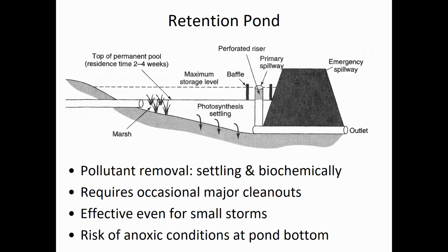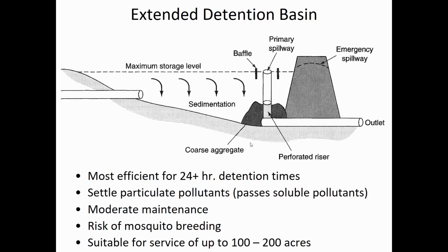But the issue here is that this extended detention basin is dry most of the time. And so it's much easier to maintain. You don't have to drain it to maintain it. You just have to occasionally, if there is a lot of sediment at the bottom, send a crew in there with a backhoe or some sort of shovel and bucket and remove the sediments.